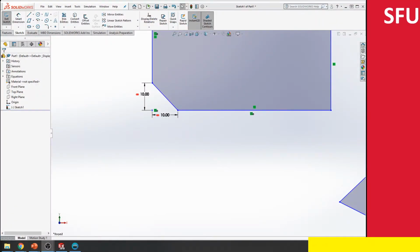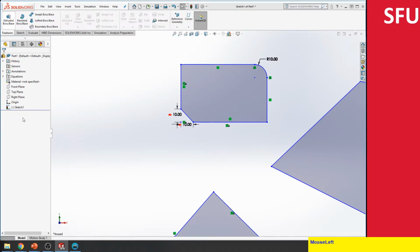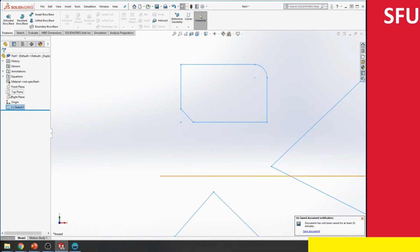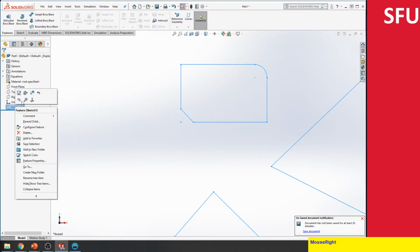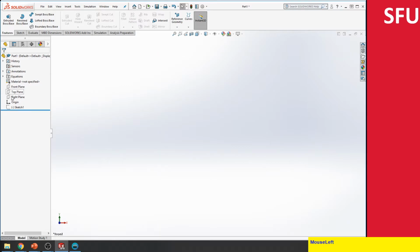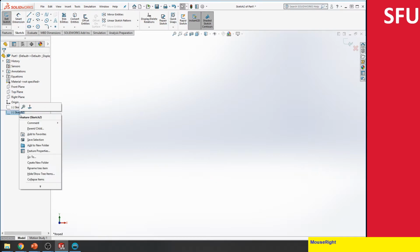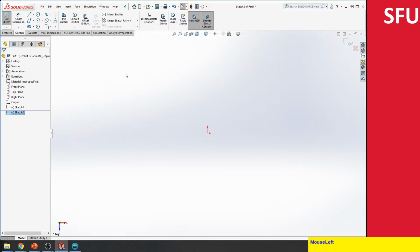So let's look at the sketch that we just created. This one actually seems to have too many parts or too many things in there. So what you can do is exit this. Now I see the sketch. If I didn't want the sketch, I can delete it, or I can just hide it for now. Let's just hide it for now. And then we create another sketch, maybe this time on the top plane, and then click on the sketch. Now you notice there's a little bit of an issue: the orientation isn't correct. So what I can do is right click and say make normal to view, and now it brings the correct orientation for me to create the sketch.